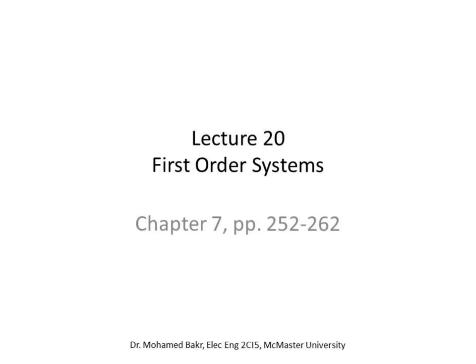In this lecture, we'll discuss the solution of first order circuits. We call them systems here, but it's really circuits. These are circuits that include only one energy storing element, so only one inductor or one capacitor. When you try to write KCL and KVL for these circuits, you will end up with a first order differential equation. So we'll see how we can solve these equations using the initial value problem.